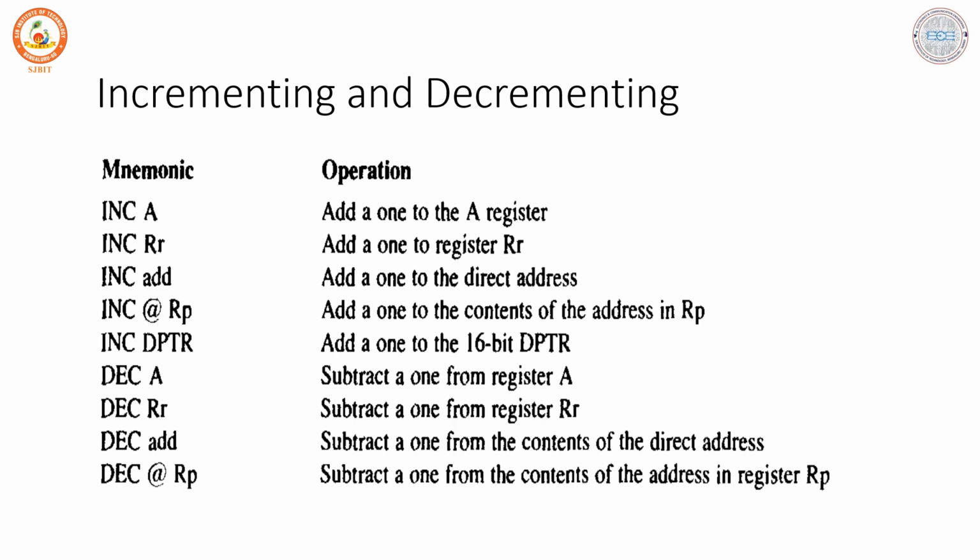These are the increment and decrement instructions, which are arithmetic instructions. They basically involve adding or subtracting one from the operand. These instructions are very useful for counting the number of times the user program travels through a certain section of code. And also whenever we want to jump to the previous or the next location, we can make use of these operations.